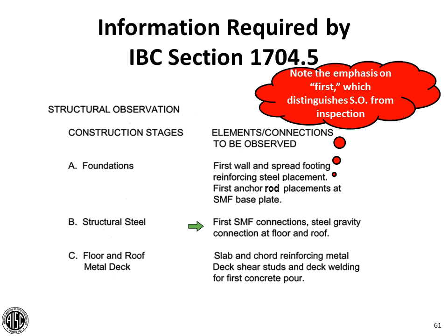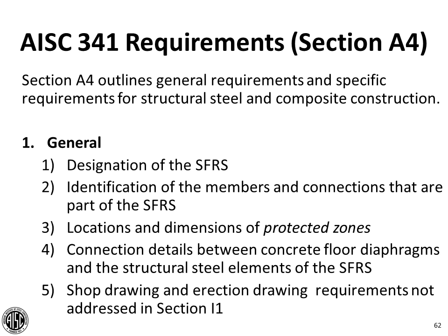There are jurisdictions that have chosen to overlook the intent behind structural observation and are requiring, or at least appear to require, the structural observer to come out every time something is done. So every time there's a placing of rebar in the metal deck and concrete slab that has drag bars or chord bars, they're saying, you need to come out and look at that. And technically that's not required. Now whether you want to fight the building department on that is something that you would have to decide based on your own project requirements.